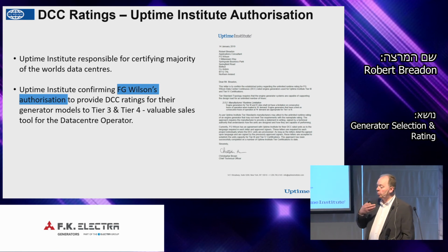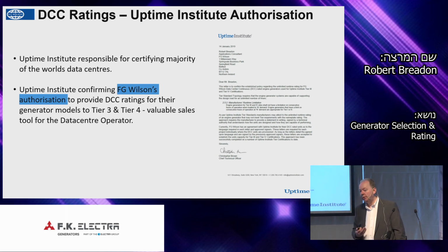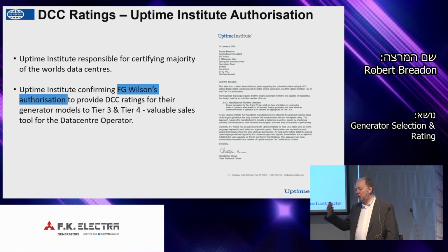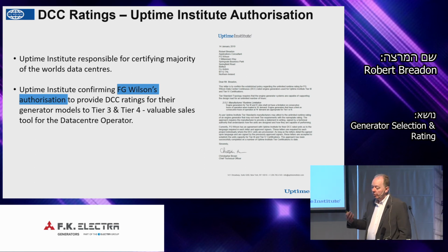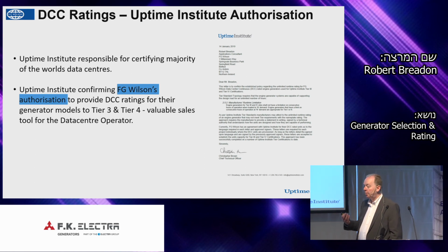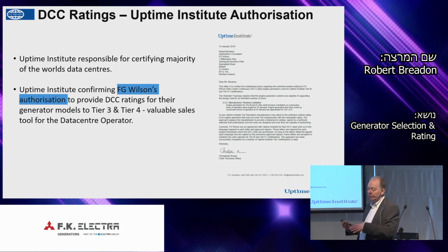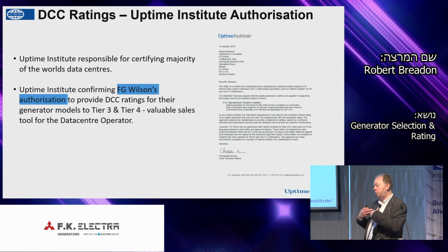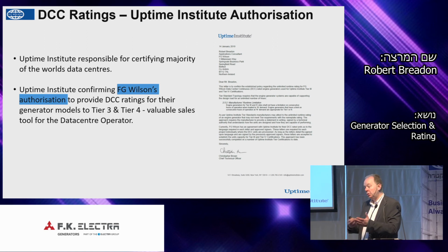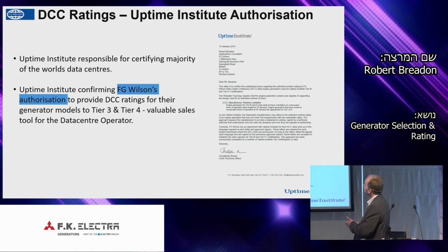When we're signing that letter, we're looking at the ambient, the altitude, the actual room location, and how it operates. Johnny referred to it earlier. We're saying the machine will deliver the particular rating at a reference point, and they usually use an international body called ASHRAE for reference data, so you must make sure your machine can deliver the ratings in that sort of application.